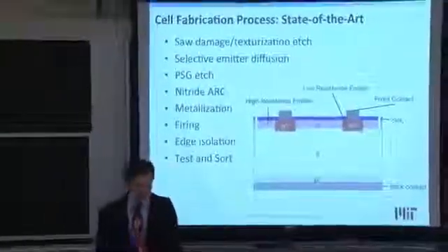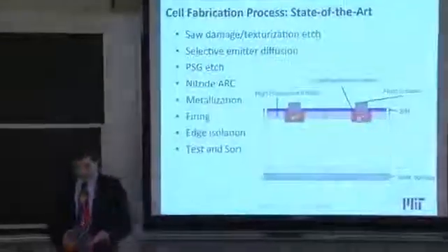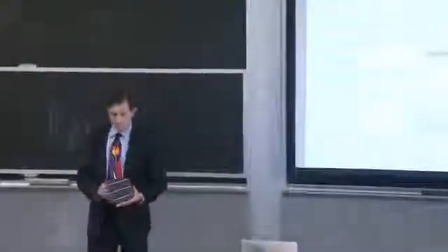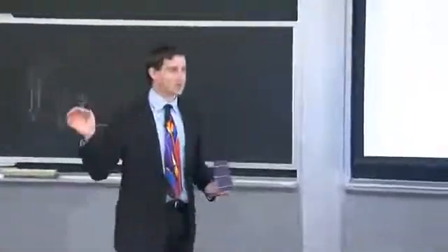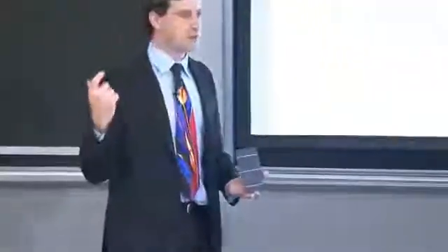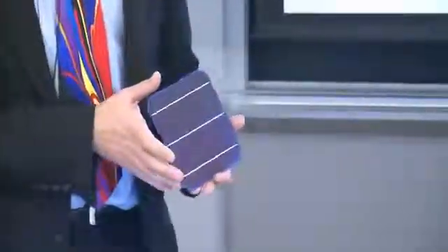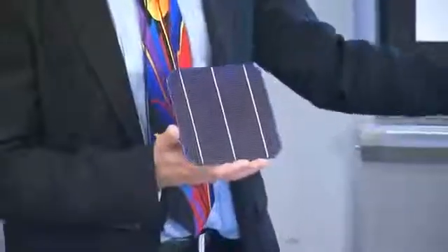And just from simple electrical engineering, and maybe as an extreme example, if you're stringing Christmas lights together, you know that if you have one bad apple, it can drag down the performance of the entire string, right, if you're connecting these in series. And so it makes sense to test each of the cells individually and make sure that you sort them together with their like cousins, right?